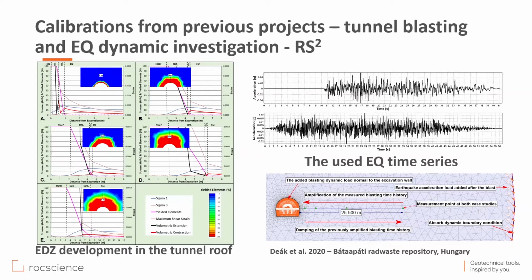Numerous variations of the two frequencies and damping ratios were modeled, and the most appropriate result was set to the measured one in our case, of course. And what is important is that, during the measurement, the conventional tunnel work was interrupted in both tunnels, and the ventilation system was turned off.